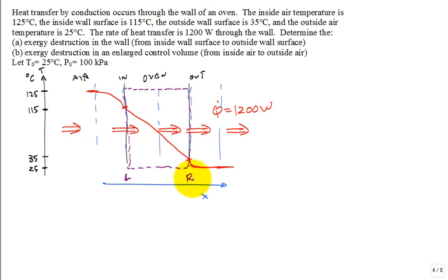And we do an exergy balance. It's steady state, so 0 is equal to, we have some exergy transfer with the Q coming in on the left side. And that's a rate at which exergy is being transferred in on the left side minus the rate at which exergy is transferring out on the right side.